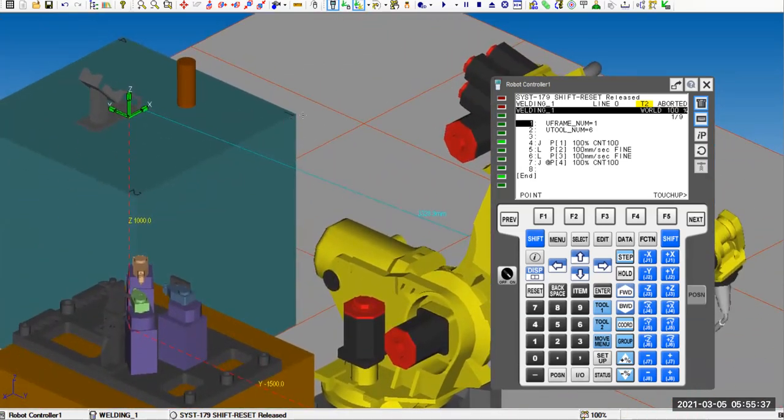Remember the user frame we set up on corner number one, right? If you want, you can redo that again. Change the tooling to pointer and use corner number one to do that 3-point method again. Then you will have a new frame set up. But because I did that with some mathematical relation, I can use direct entry to change the user frame right away.